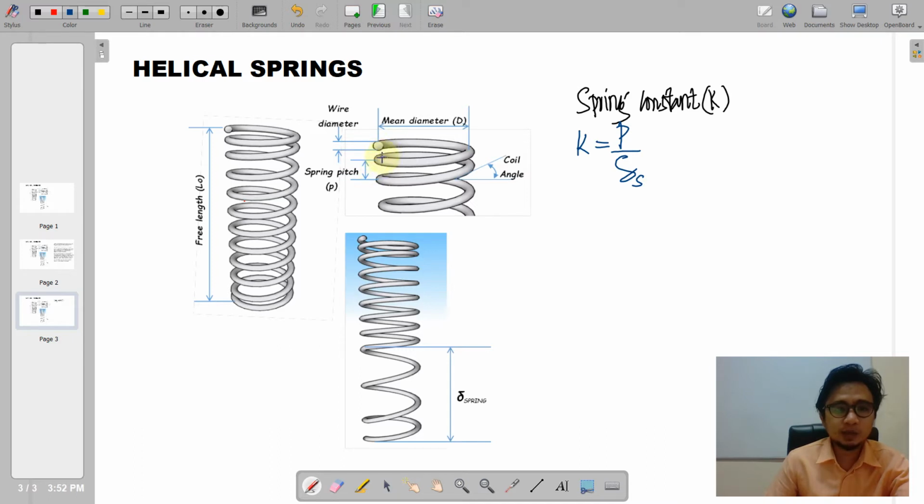As for the mean diameter, when we say mean diameter, or the capital letter D, it is the diameter formed by the helix out of wrapping in a cylinder. It is measured not on the edge but at the center of this cross section. So center to center of the cross section, that is the measurement of the mean diameter of the spring. And this is related also to the rigidity, as we are saying, G d^4 all over 64 R^3 n.